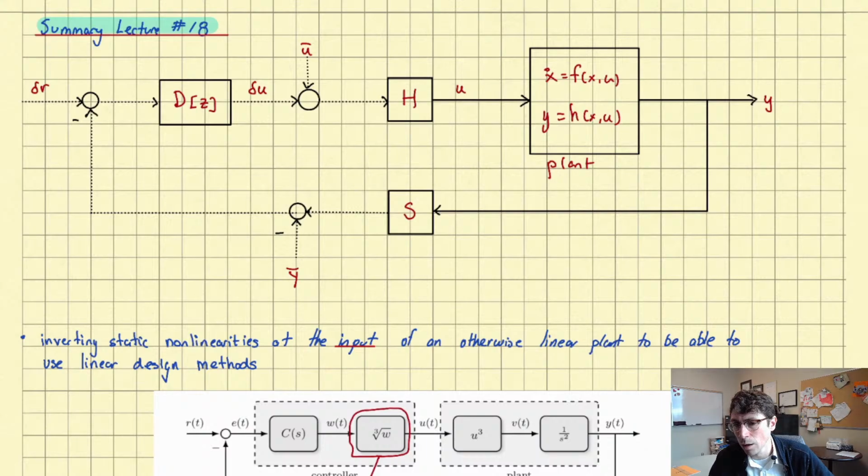In terms of Chapter 5, follow the spreadsheet that's on Learn to see which sections of the notes are fair game. Last time we were talking about control design based on linearization. This was the idea where you approximate your nonlinear plant using a linear model near an operating point or an equilibrium configuration. You design the controller for the linearized model, and then you use it to control the original nonlinear system. And the most important point of what we discussed is the picture shown here. This is a picture of how you would implement the controller that you've designed on the nonlinear plant. You should understand what this picture is about.